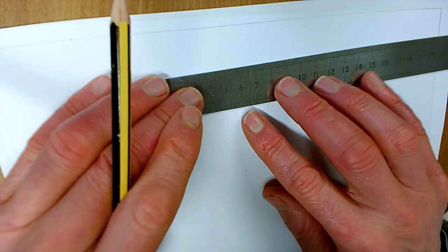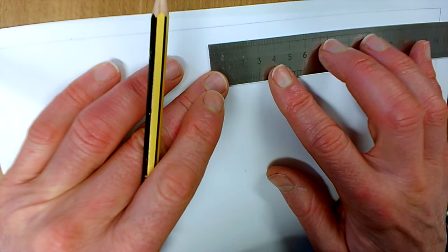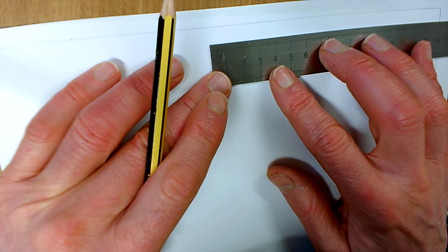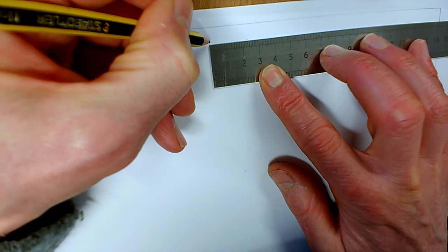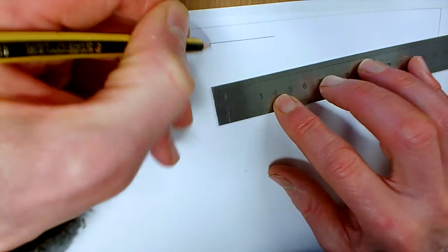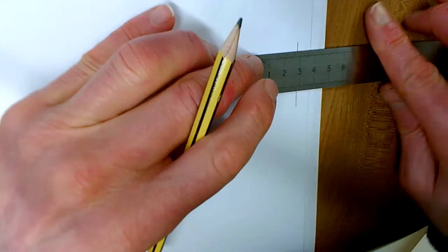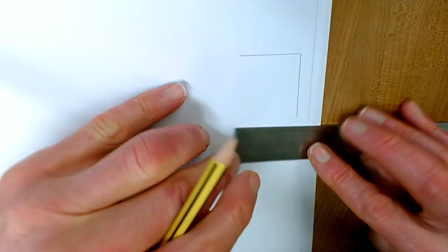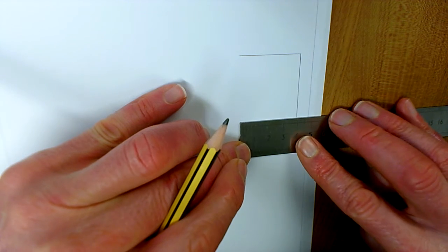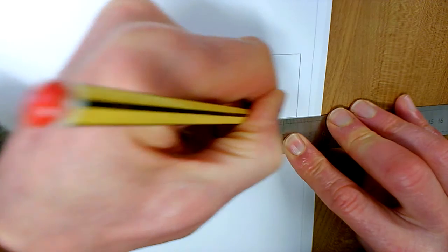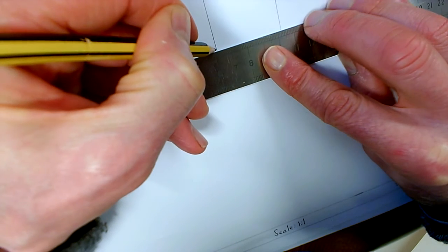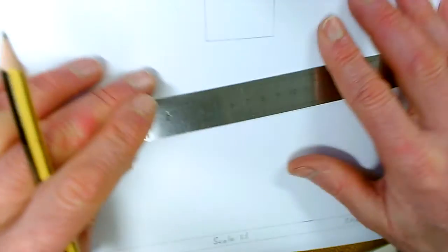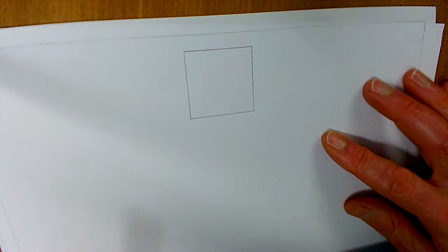I said 45 millimeters, didn't I? Remember, we're drawing this at full scale, so it's going to be 45 millimeters on your piece of paper. So I'm going to measure 45, and the depth is going to be 40. So I'm then going to draw 40 like so. My top view of this is just going to be, I would say square, but it's not really a square. It's rectangular. It's more square-like, because there's only a slight difference between the measurements for the width and the depth. So that's my plan view done. Simple as that.